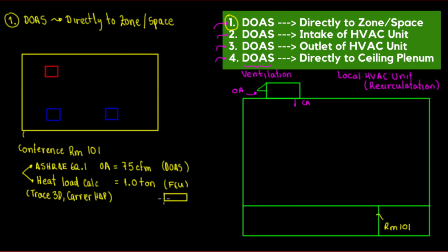All right, and this is going to be on the ceiling. Okay, so 1 ton, and then my CFM for this, we were saying, is going to be 370 CFM. So technically this space, which is the conference room, has to be very quiet, and we're going to have 370 CFM. So we can split this 370 into 2 diffusers.